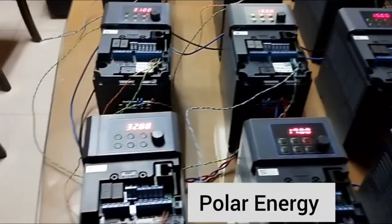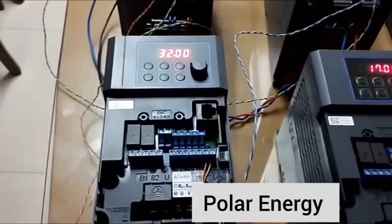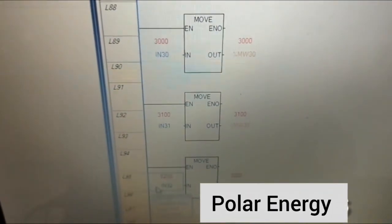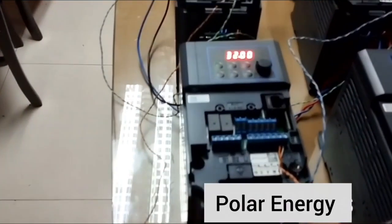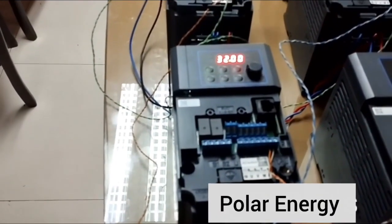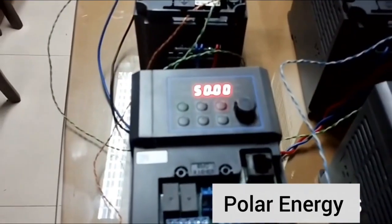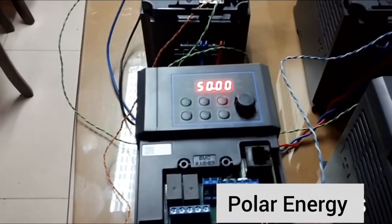So, for example, let's change the value for this inverter, which currently has a station address of 32. I'll set its frequency value to 50 Hz, and if I confirm this change, you'll see that the inverter's frequency updates very quickly, and it is now successfully set to 50 Hz. This demonstrates how easily we can adjust these parameters in real time to meet our operational requirements.